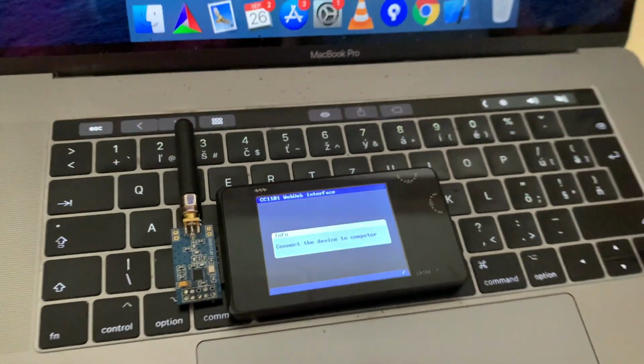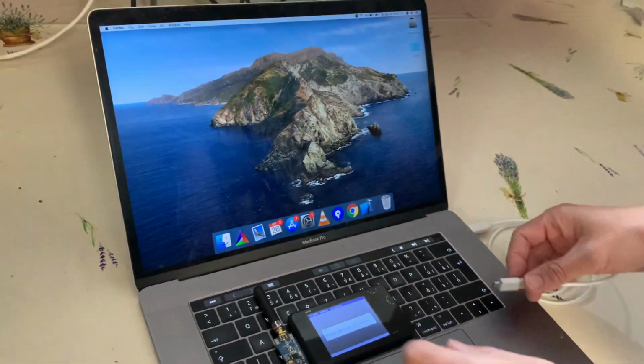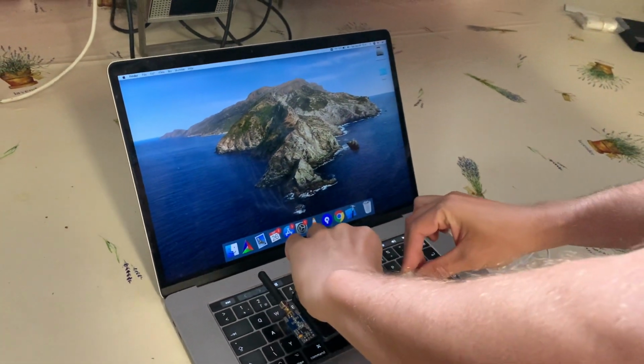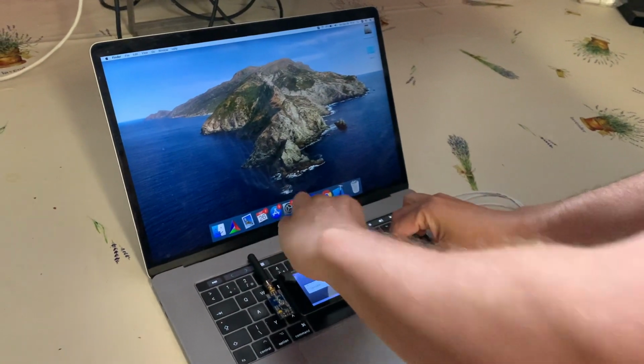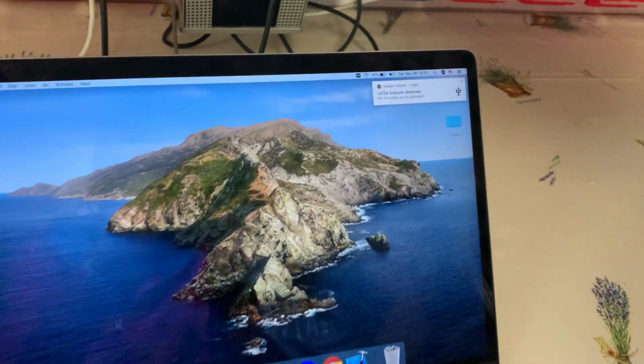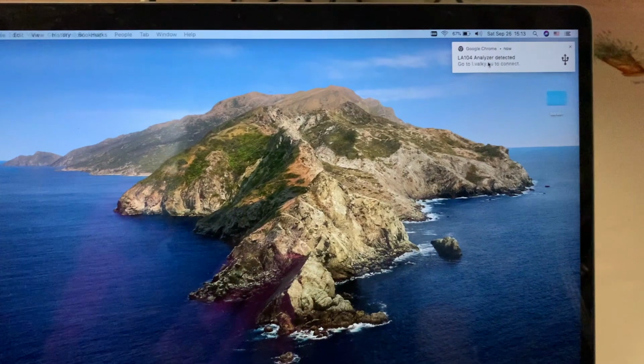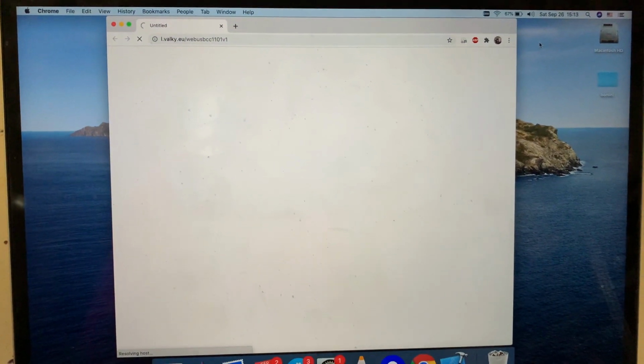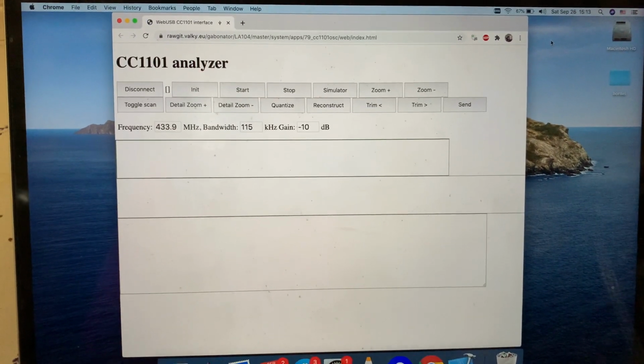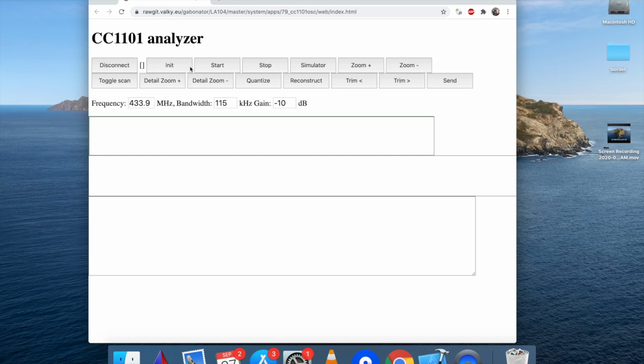This toolkit currently decodes 5 different modulations, but its compatibility can be very easily extended. For this purpose, there is WebUSB signal analyzer application running in web browser, which shows the radio signals in great detail with timing diagram in microseconds, and offers all necessary tools for identifying the modulation type and helps to design new demodulation modules for RF Toolkit.